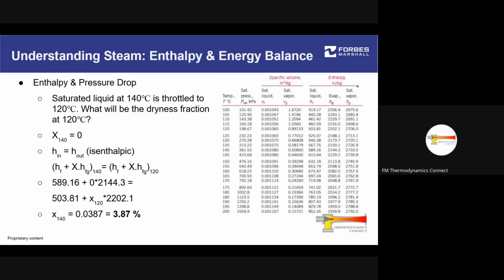Now, this is just an example. In industry, you will find many examples like this, where you will have some amount of vapor conversion, which we call flash steam. So here you will always get some quantity of flash steam coming out of the process. The problem is, if I have any flow measurement system associated with condensate, associated with saturated liquid, every time there is a pressure drop like this, so here the pressure drop was from 3.6 bar absolute to about 2 bar absolute, or 2.6 gauge to about 1 bar gauge.